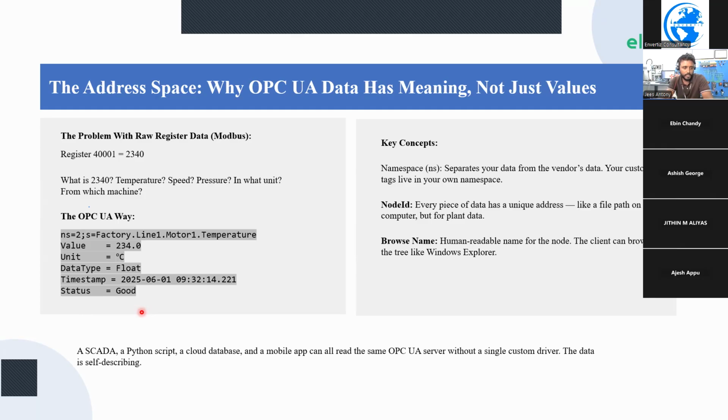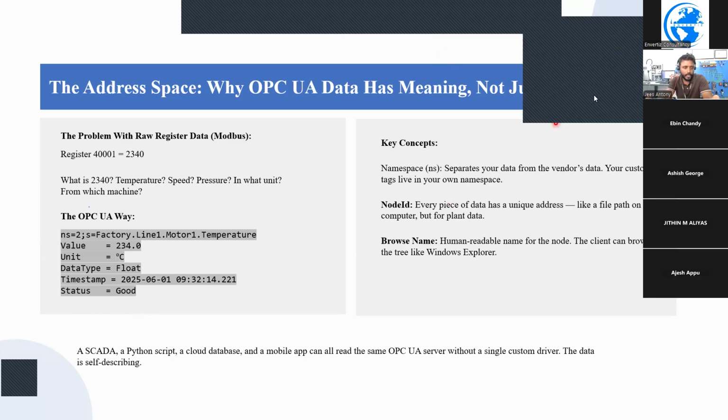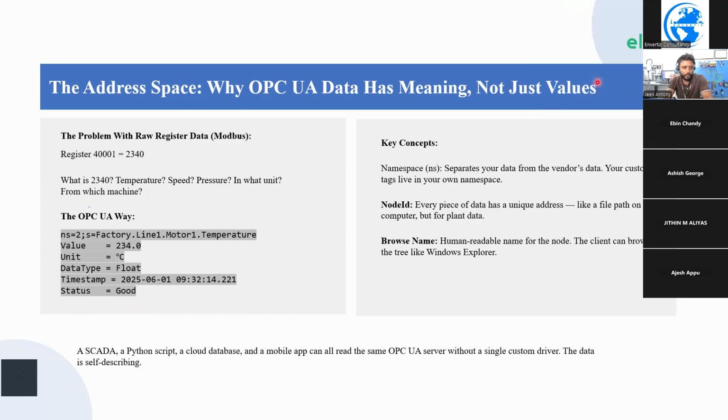With OPC UA, we can very easily achieve this. If you use any other standards, you have to make it by yourself. You have to keep the standard by yourself. Maybe you have to keep that standardization of data sharing between controllers. If you're using any specific vendor protocol, you have to keep your documentation separately. But with OPC UA, this standardization of data exchange is standardized across the industry, and it is maintained by international organizations, so that when an update comes, everyone who follows this OPC standard will be updating their own controllers, or their own implementation of OPC in the devices will be updated as well.